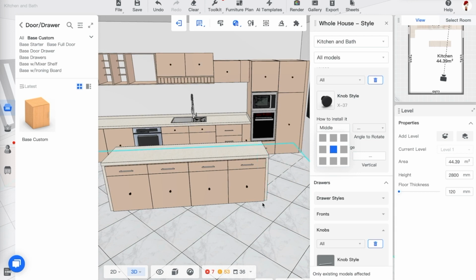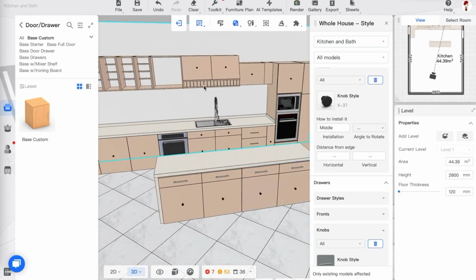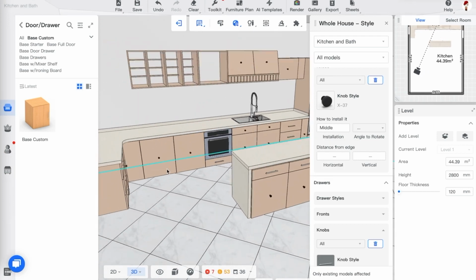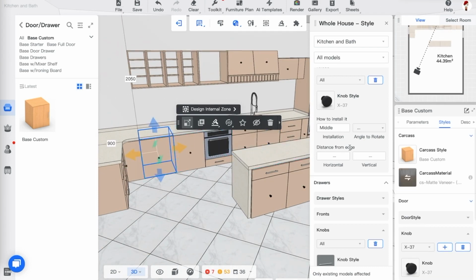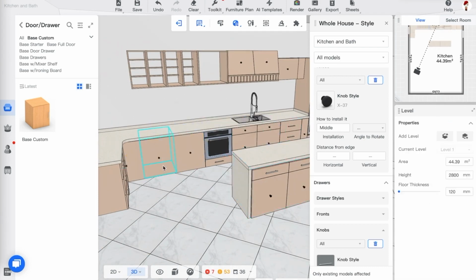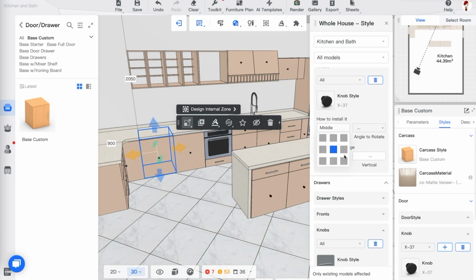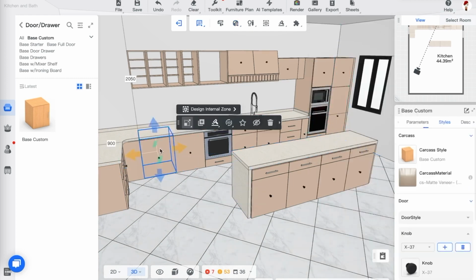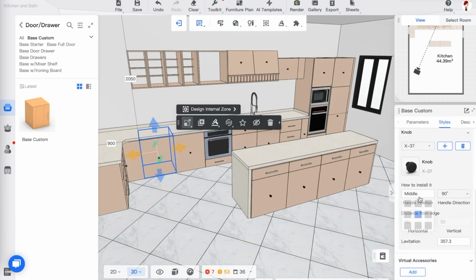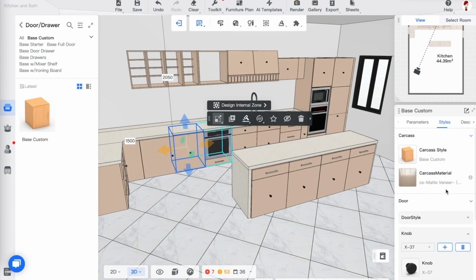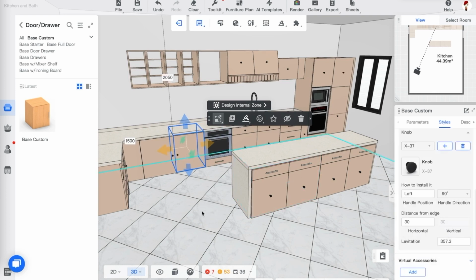Usually it's not recommended to do a global change of this, because for a lot of cabinetry the location of the knob doesn't necessarily need to be on the side. So, for example, for this one, I'll probably have to move that to the lower right. I just moved off the global style again. Let me exit out of here, click on here, and here are the knob locations. This is where I'm going to be placing the knob. Same thing here, you just have to manually fix it.